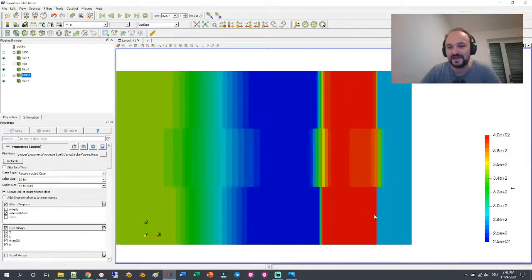It's the same, so we have a very nice jump in the temperature, pressure, velocity with the finest mesh, a good discontinuity with 1000, and the horrible discontinuity with 100 cells. So this should show you what the grid refinement does and why it is so important to run a grid dependent study in each project at least once to understand the behavior of your numerics on different grids and what is reasonable.